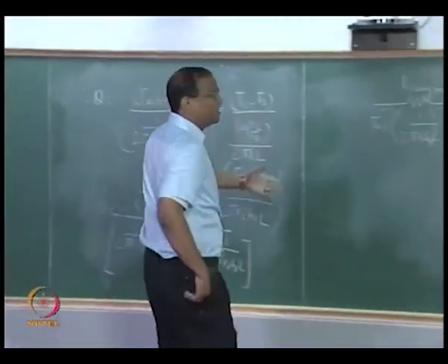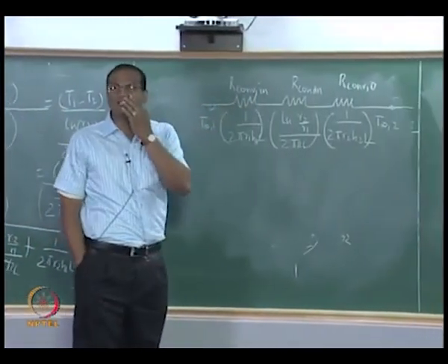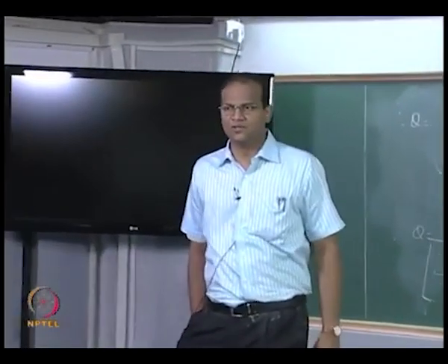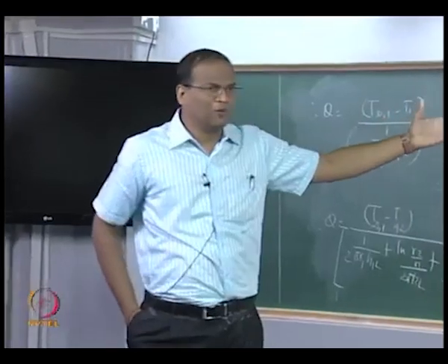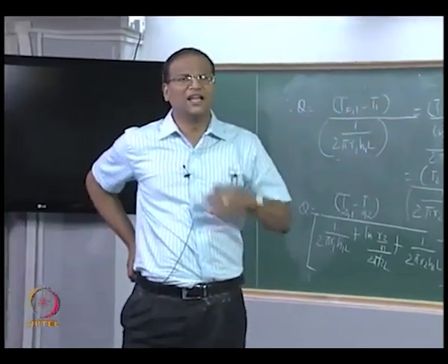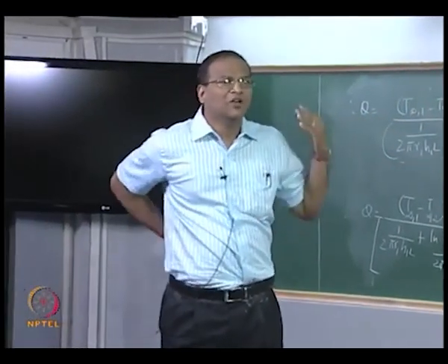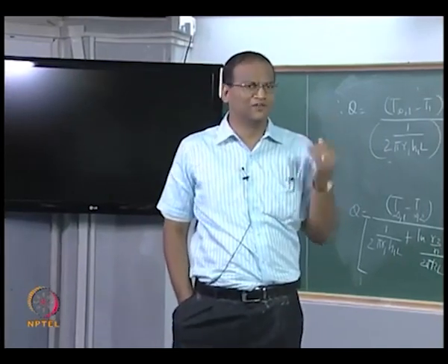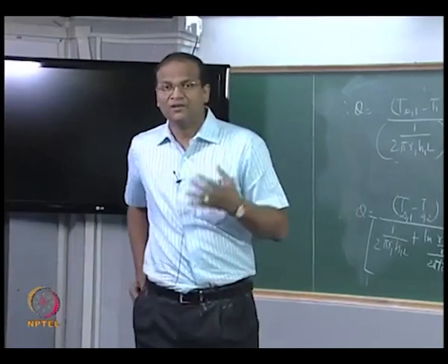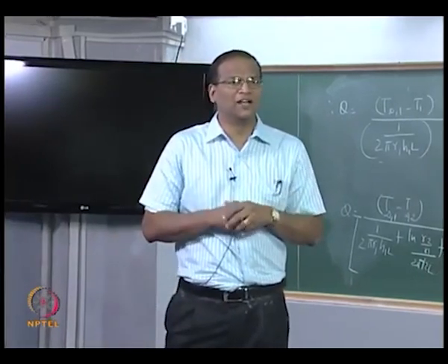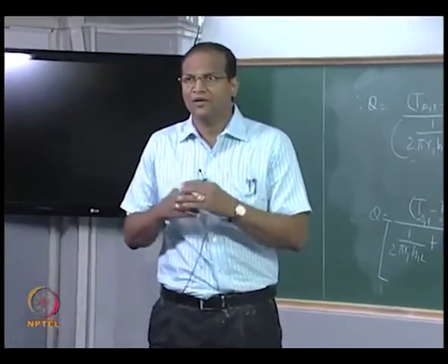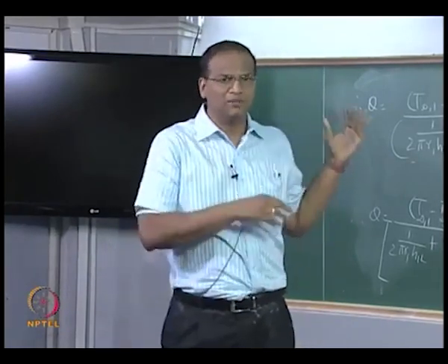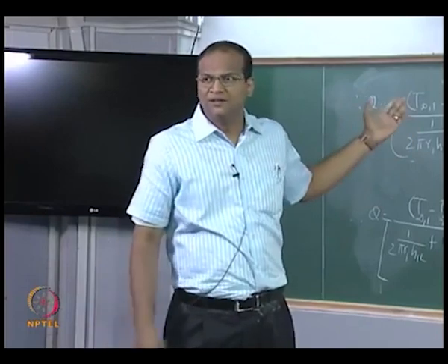There is also a point you can work out, what is called the critical insulation thickness, which you must have done in your undergraduate heat transfer course. So we can use the dividendo componendo rule and arrive at results like this. In an exactly analogous fashion, you can derive basic relations, analytical solutions for one dimensional heat transfer across a spherical shell. Why is a spherical shell so important? Because you want to carry cryogenic fluids, you want to carry nuclear fuel waste and all that, and then if you want to put several layers, then there can be Ka, Kb, Kc.